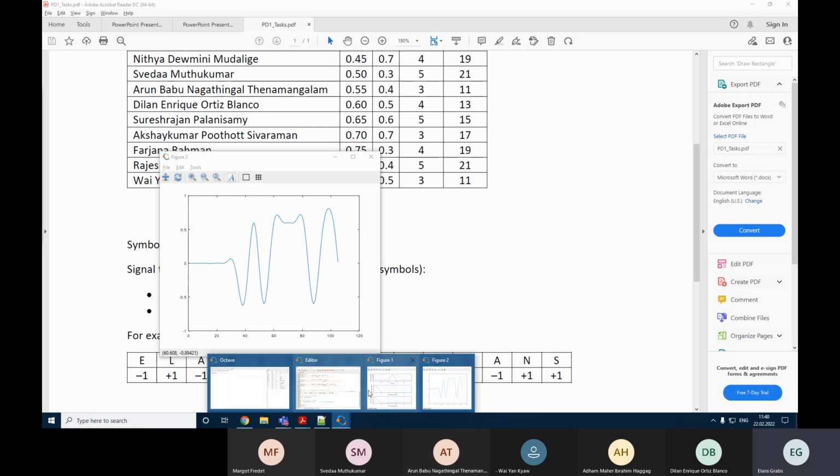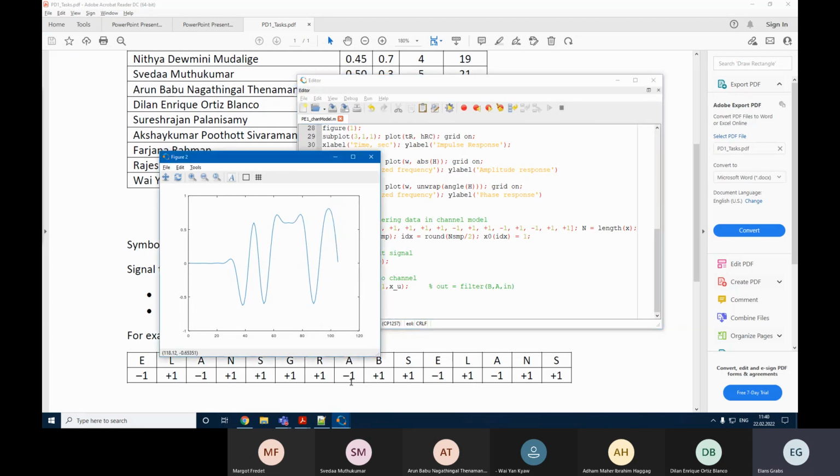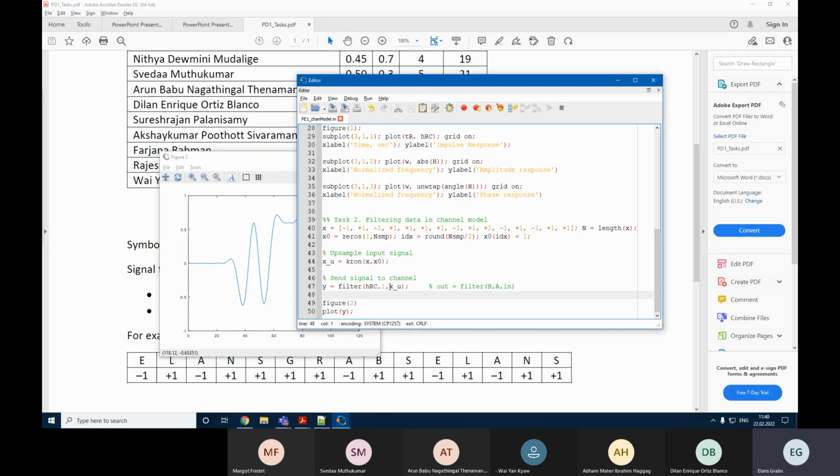So in order to get the full signal, not just the first part of it, we need to actually, during this filtering, append zeros to the end of this signal. So we are going to append some zeros by specifying it as a new array consisting of our existing array, followed by some zeros. And in particular, we want to append exactly delay zeros. So for that reason, we calculated that variable, among other reasons, so that we append zeros to calculate the full signal.